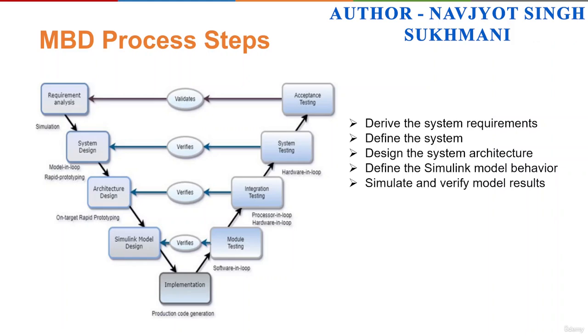Generate production code automatically. That's the next step, how we can generate the production code automatically. From the Simulink model block diagram, the production level code is generated automatically. After the host hardware settings have been considered, for example, fixed point properties are set for fixed point system. The code can be generated to deploy on microcontrollers like PLC, FPGA, ASIC, and so on.